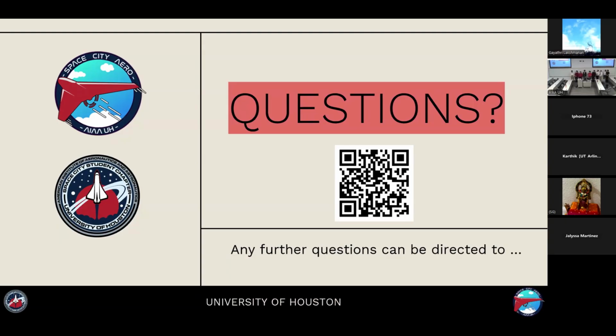Another thing, and then I'll pass it over to Andrew. Why DIY landing gear? Why not just buy it off the shelf? We originally were going to do commercial off-the-shelf landing gear. We thought, yes, why would we make our own? We could just find some. It is actually surprisingly hard to find landing gear with the ground clearance required because we have to have at least 8 inches of ground clearance for the banner system in our problem.